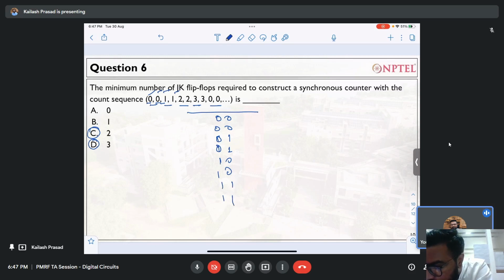So these are the 2 bits which will be representing the individual numbers. But what we have to do is differentiate between this 0 and this 0, right? These are two different states, and for differentiating, suppose I am taking two variables, b and c, for representing the 2 bits. I have to take another variable a, which will not be used in the state machine, but for differentiating.